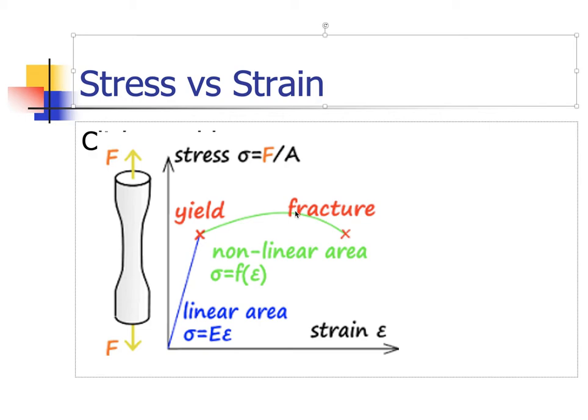Okay, so the stress strain diagram, we can load it all day long, up and down here. It's linear, more or less, and it just goes up and down. Okay, once I go past a certain yield point, then it starts to elongate more than it should. And if I unloaded it right now, it would go down to right about here. The elastic relaxation will be the same slope as this going up. It would just make a big box here. Boop. And then if we want to load it again, it would go up to here and then continue along this path.